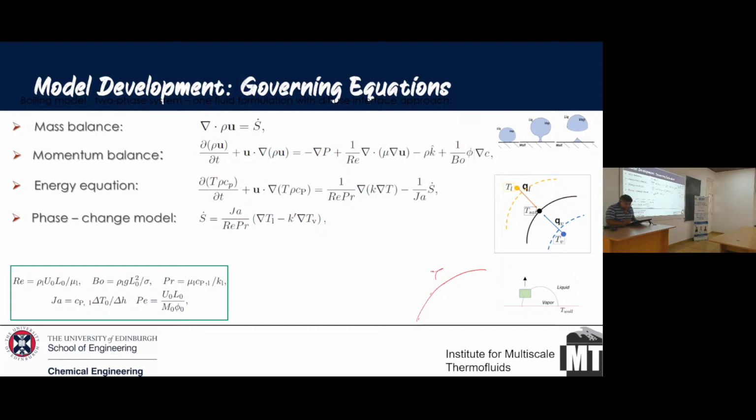In case of boiling, this is a constant temperature. So you're not even worried about surface tension. There is no such thing as Marangoni effects in boiling because the temperature is constant. If your water is boiling at 100 degrees Celsius, your interface is at 100 degrees Celsius. Water boils at 100 degrees Celsius to develop steam at 100 degrees Celsius. So all it is doing is change of state. That's what we're doing here as well.